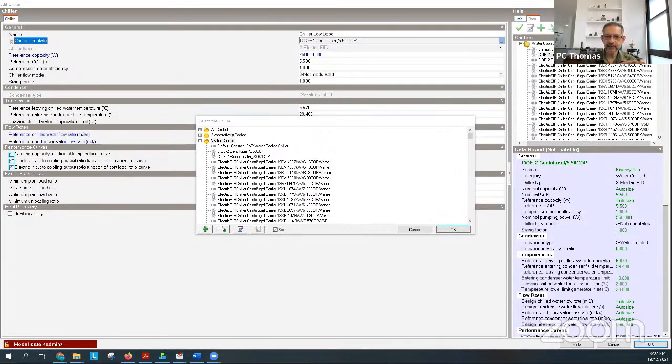It says there are four points on a standard curve, and it takes an average of when the chiller is running at 25% for so much percentage of the time, 50% for so much, 75% for so much, 100% at whatever, and then it gives you a value. Now you can compare two chillers and their IPLV ratios. However, that has no relationship to how your building is requiring cooling.